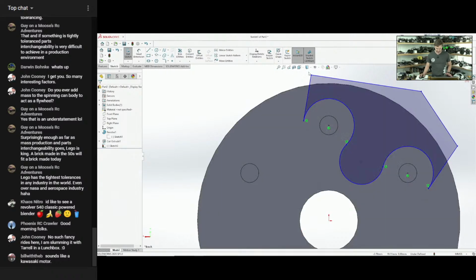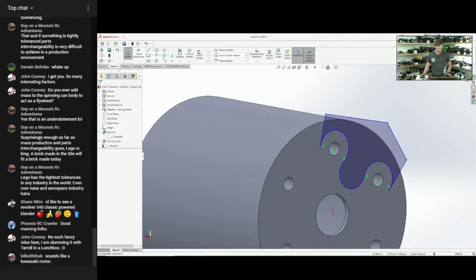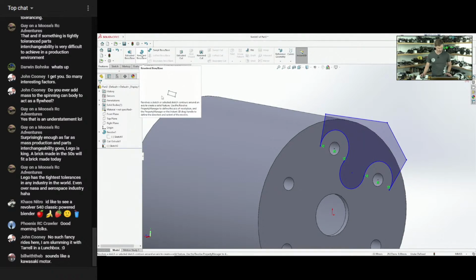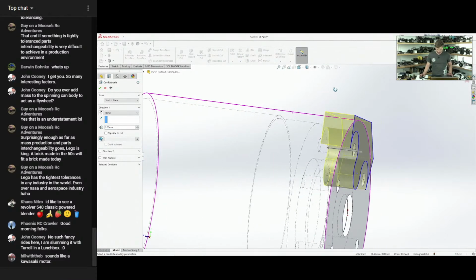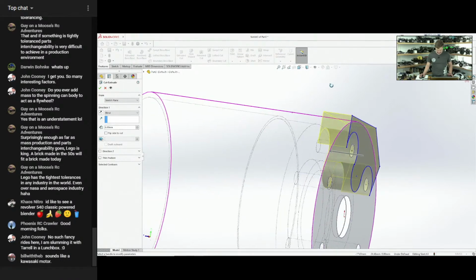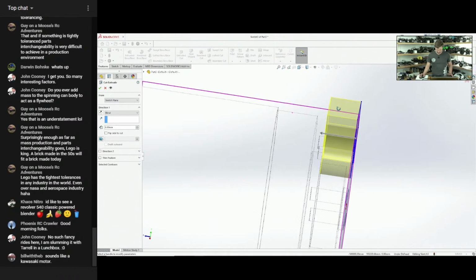We're going to go back to this mode, turn a little sideways, and now what we can use is the extruded cut. There we go, extruded cut. I know that we only have 7 millimeters to work with. I'm going to say 6 millimeters, so that it doesn't get into any of our good stuff. That should give us just enough room.